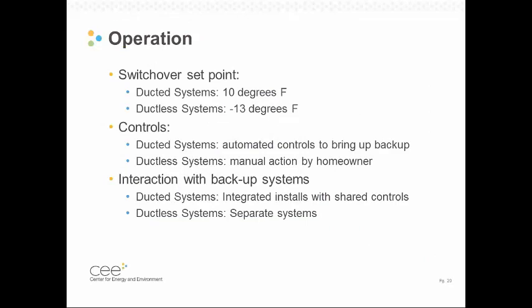In terms of operation, you're going to have slightly different operations for the different types of equipment, for the ducted systems or the ductless systems. As we mentioned in that sizing chart, for the ducted systems, we targeted about a 10-degree switchover. And that's the point where the heat pump can no longer meet the load at the house.